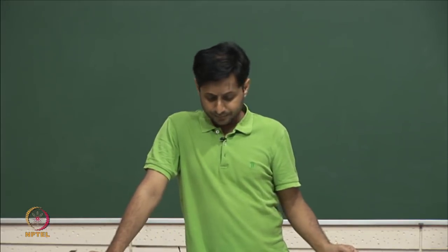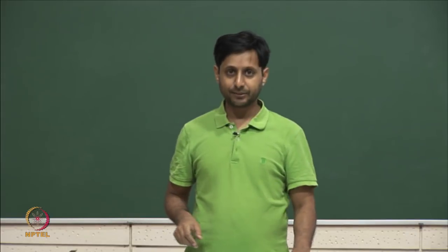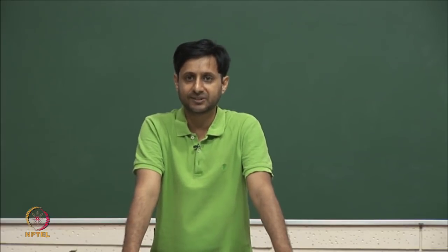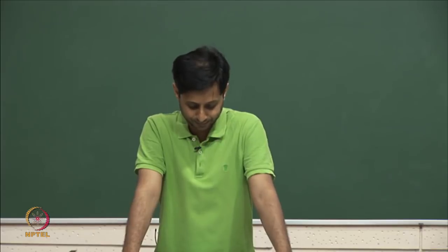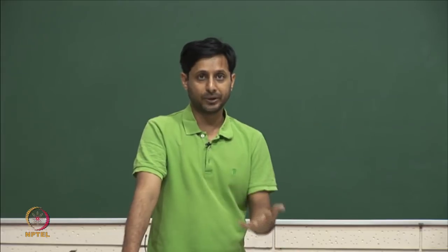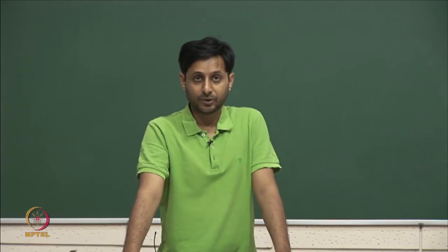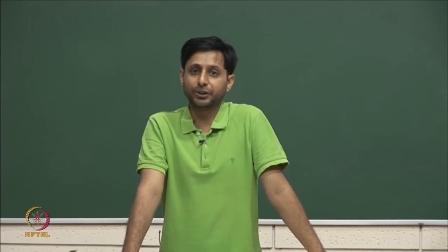Okay. Let us stop here. We started with the plan that we will do both common source, common drain and common gate amplifiers, but we managed to do only the common drain circuit, the common drain amplifier. It is not a voltage amplifier, it is more like a power amplifier, right, and it is also called the buffer circuit. We saw the interaction of the body, right.